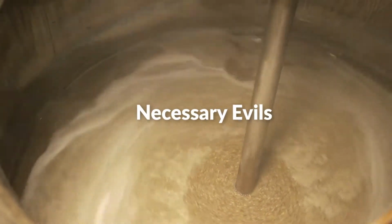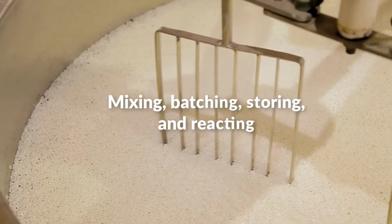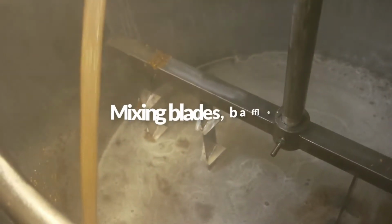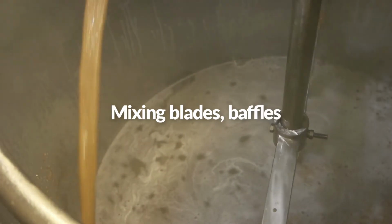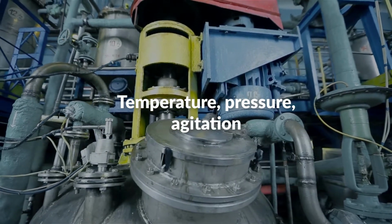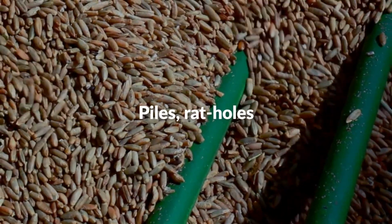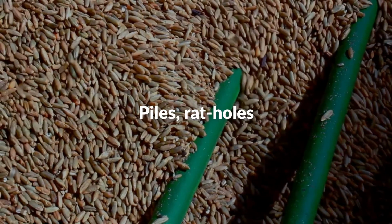Part of the problem is that level measurement comes second to the primary tasks of mixing, batching, storing, and reacting that take place within vessels. So the conditions inside the vessel are determined by a process engineer. For example, a reactor may require high temperatures, high pressures, and vigorous agitation, and the level instrument must be chosen to accommodate those conditions. If the solids in a silo tend to pile up in one place or form a rat hole, there may be no true level to detect.